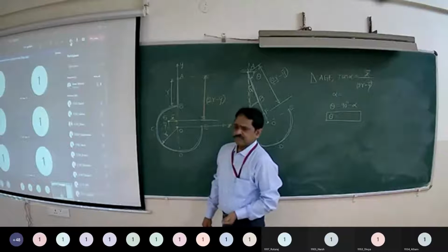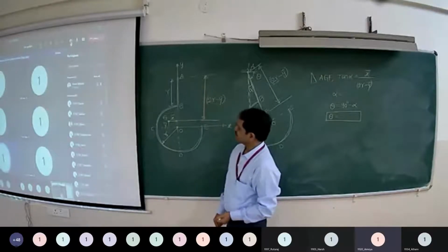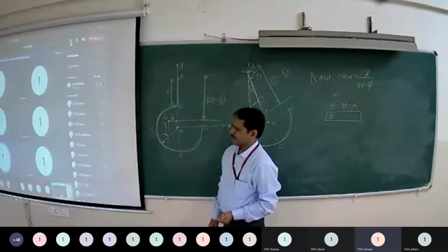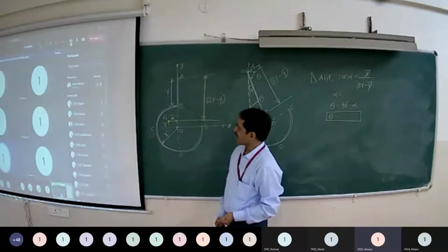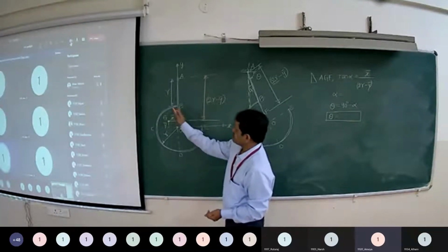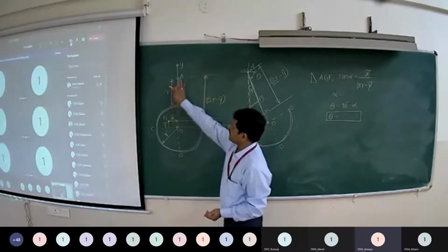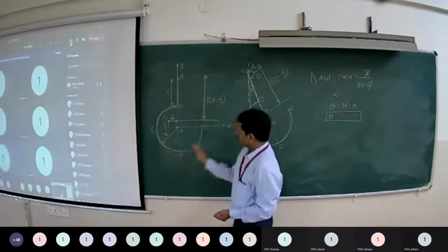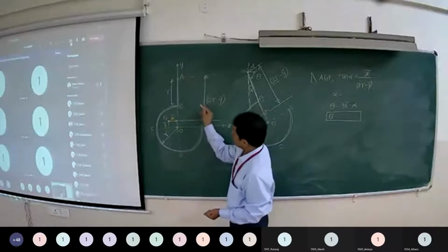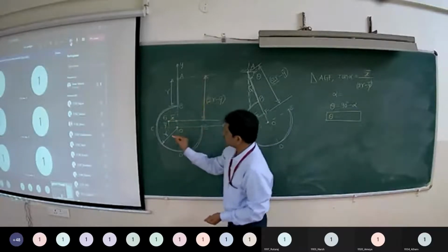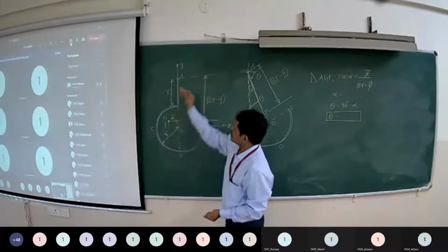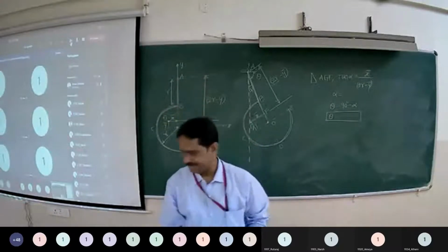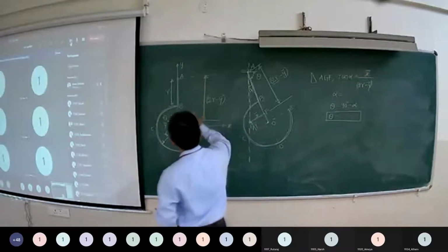But the portion of the circle is not removed uniformly. So I think it makes intuitive sense that it would lie on the angle bisector of this 270-degree angle. Yes, but this addition AB is there. After that AB, then it will come upwards. Right. Suppose if there is no AB, you have only these 3/4 of the circle, then the center of gravity will be located as you said on this line here. So as we are adding AB, it will be shifted towards the addition. Right?